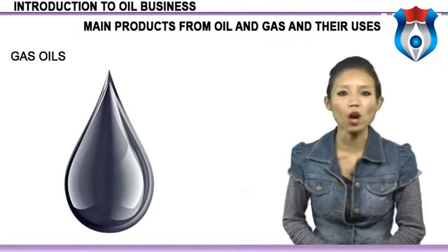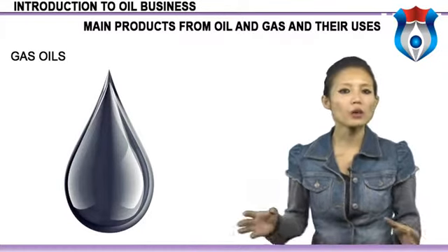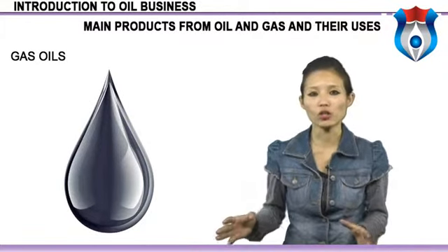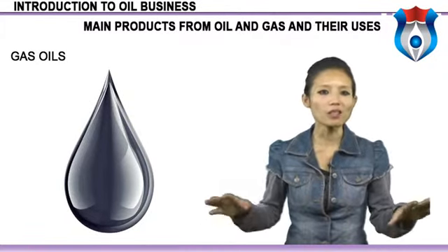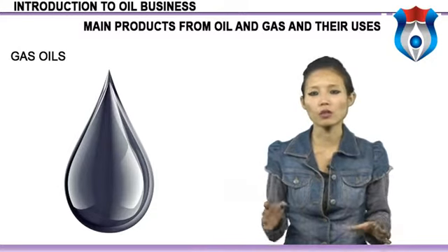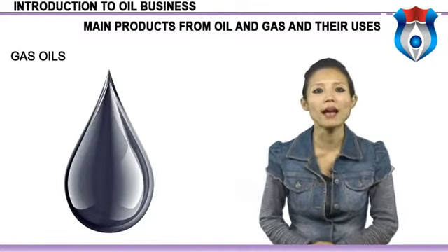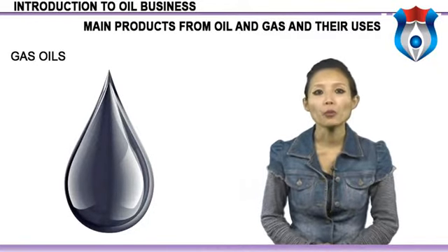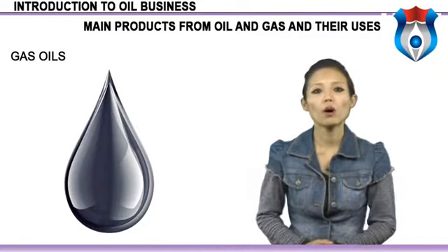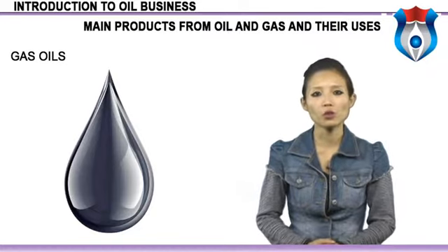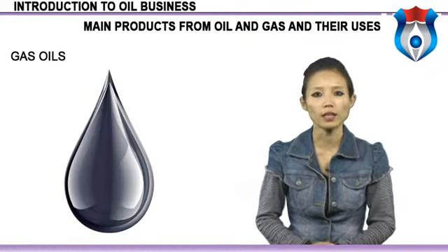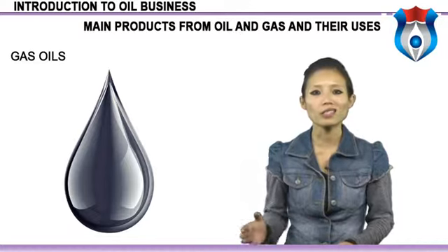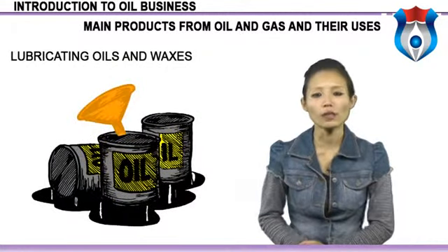Diesel engines are compression ignition engines and work differently from combustion engines. Long chain paraffins that knock badly are very good diesel fuels. Vice versa, branched and cyclic hydrocarbons can be excellent gasoline but form poor diesel fuels. The quality of diesel fuel is referenced to cetane, normal hexadecane, C16H34.